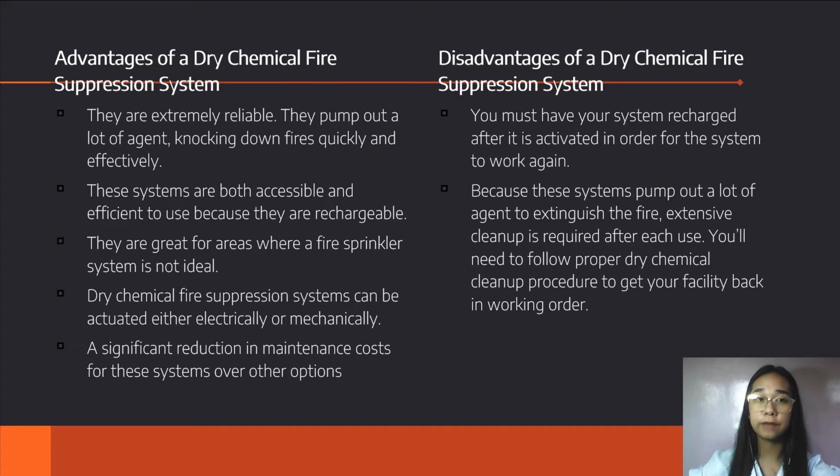Now, the disadvantages include that the system must be recharged after it is activated in order for the system to work again. And because these systems pump out a lot of agent to extinguish the fire, extensive cleanup is required after each use. You'll need to follow proper dry chemical cleanup procedure to get your facility back in working order.